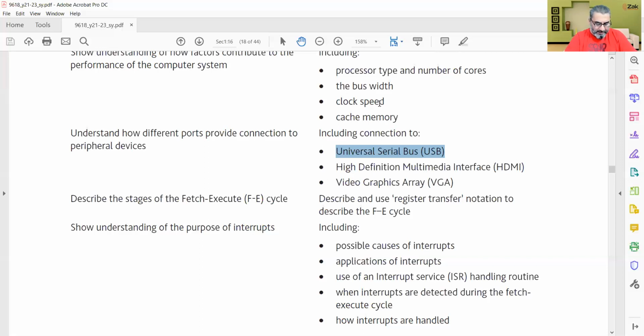The USB is an asynchronous serial data transmission method. It has quickly become the standard method for transferring data between computers and a number of devices. All right, the USB cable consists of a 4-wire shielded cable with 2 wires for power and the earth, and 2 wires used for the data transmission.